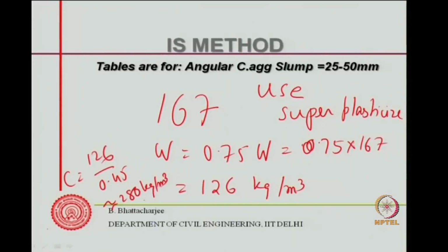So you see, you have a saving in cement as well. Water is less, cement is less. That's why I wanted to show that if you use superplasticizer, for the same workability you can save on the cement, which we have seen earlier when we were talking about admixtures.